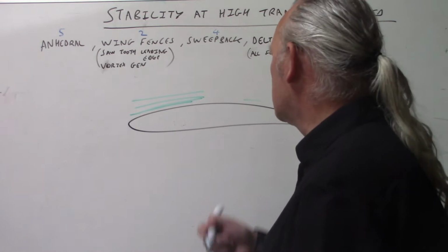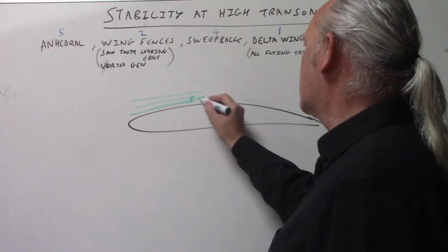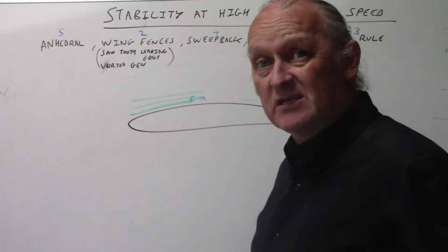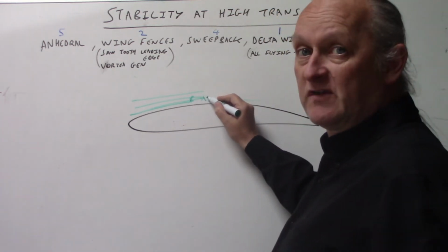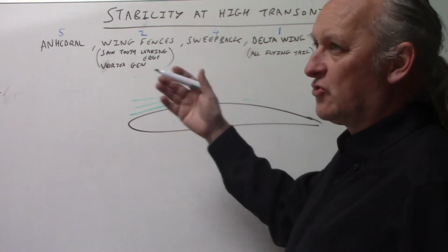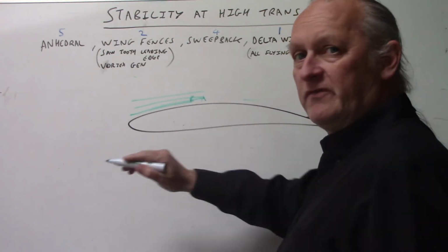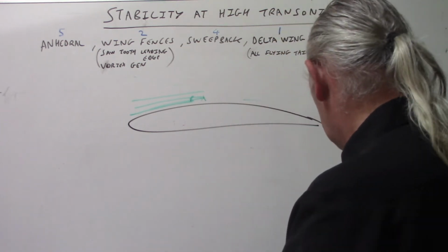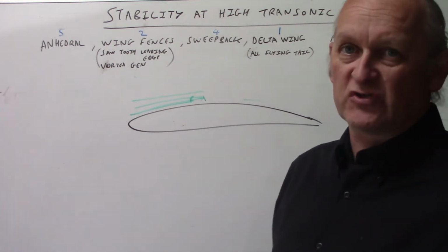And how the shock wave builds up is this: air particle A is going as fast as it can. Air particle B catches up with it, shoves on the back of it, pushes against it. We want to go supersonic as well. I'm going as fast as I can. Not supersonic, they're going at sonic velocity. So the air particles are being accelerated over the wing. They cannot move any faster, so they form a shock wave. They collide together and they start to compress. And this is what we talk about, the compressibility of flow.